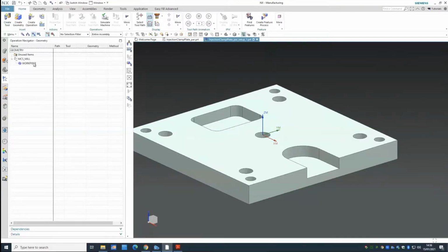So whenever you design a part, and you've done it in the first semester, you have your own coordinate system. It's a workpiece coordinate system that you have. The workpiece coordinate system is for the part, and because the CNC machine, again, has its own geometry, it still has its own coordinate system that it wants to operate with.